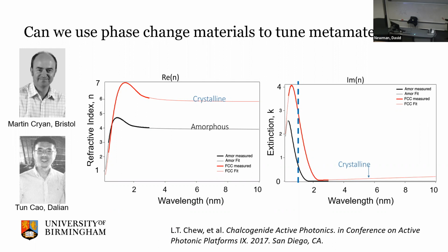And in 2012, we rolled out a whole bunch of papers showing the potential of phase change materials, data storage phase change materials, mostly in the infrared, where we were controlling the phase of the light rather than the absorption, based on GST controlling resonances in meta-atoms. We were mainly trying to operate above 2 microns, where the absorption is minimal and we're just having this change in refractive index.